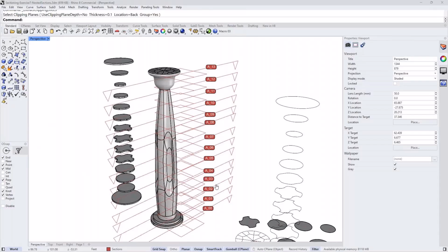That's a good question. I think instead of extracting slices, I would extract sections. This way you already have the curves instead of having to flatten those. I know you'd like to capture the maximum, but that is going to be if you have a more dense kind of slices. The problem with that is that you have tapers in two directions. You have some tapers that are smaller going up and some that are larger going up. So you need to capture both the top and bottom of each slice and then project onto a 2D plane to figure your outline for your laser cutter.